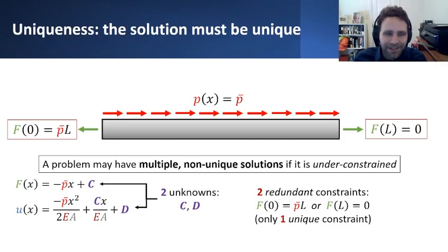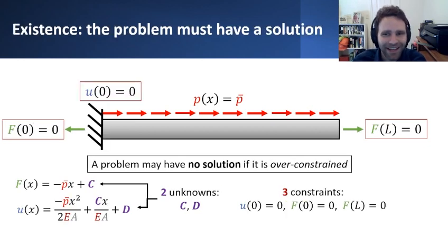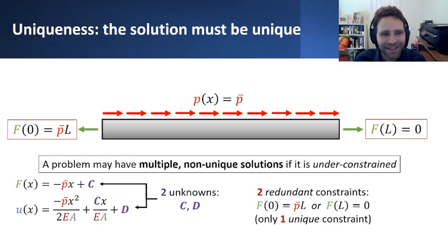Solution uniqueness. Now this one might be a little bit tempting to say, well, if I didn't like the way that I was defining things previously, maybe I wanted to go about doing things a little bit differently and say, let's just get rid of that displacement boundary condition. And if I already kind of know what the reaction force should be there, let's just put the reaction force there. And shouldn't that satisfy equilibrium? I have 2 equations now, 2 constraints that I'm imposing via boundary conditions. Should this not remain in a state of equilibrium? And should I not obtain a unique solution for this problem?